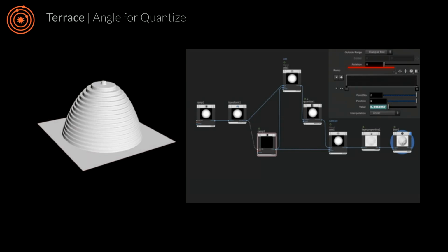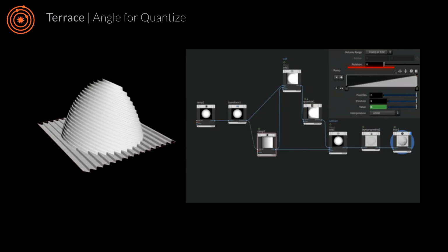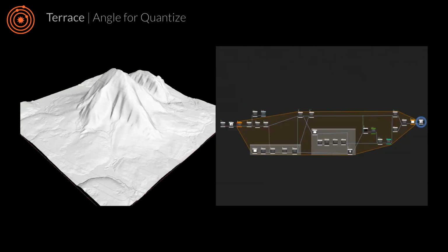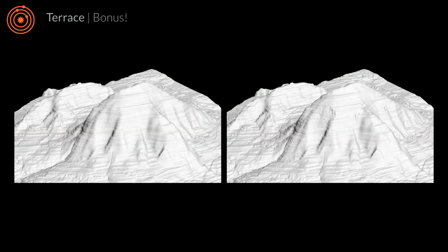And this is something Tom Goffelli helped me with, also one of the developers at SideFX, who is a great guy. And I'm very grateful for this idea. And now we can add it back to our original little loop here. And if we preview how it looks after 50 iterations, you can see now we have a bunch of terracing happening, and specifically they're randomized on the y-axis, so they kind of look in different directions, but at the same time, they follow the same angle. So that's already quite interesting for me, and it looks quite fun. And we can go to the next step.